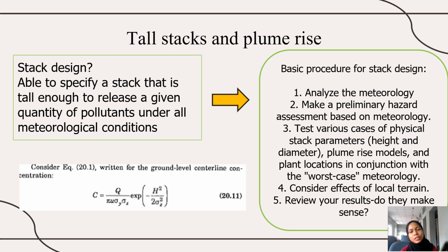The basic procedure for the stack design: the first one is we need to analyze the meteorology and make a preliminary hazard assessment based on meteorology. Then test various cases of physical stack parameters, height and diameter, plume-rise models and plant location, and consider effects of the local terrain, and review the results, and see whether tall stacks and plume rise make sense or not.